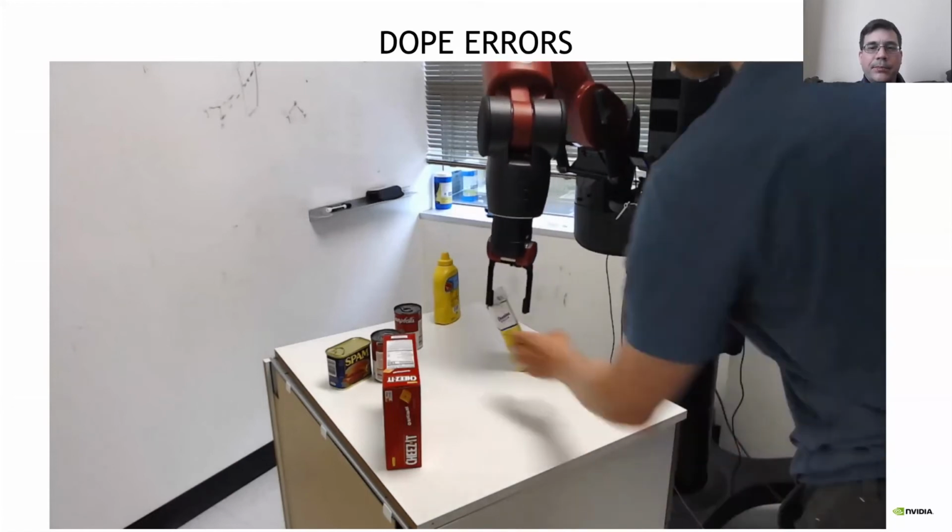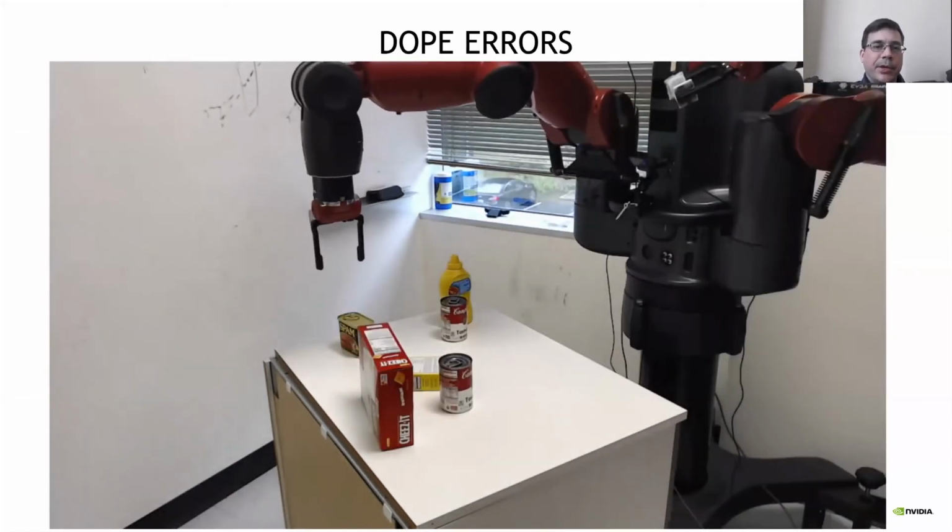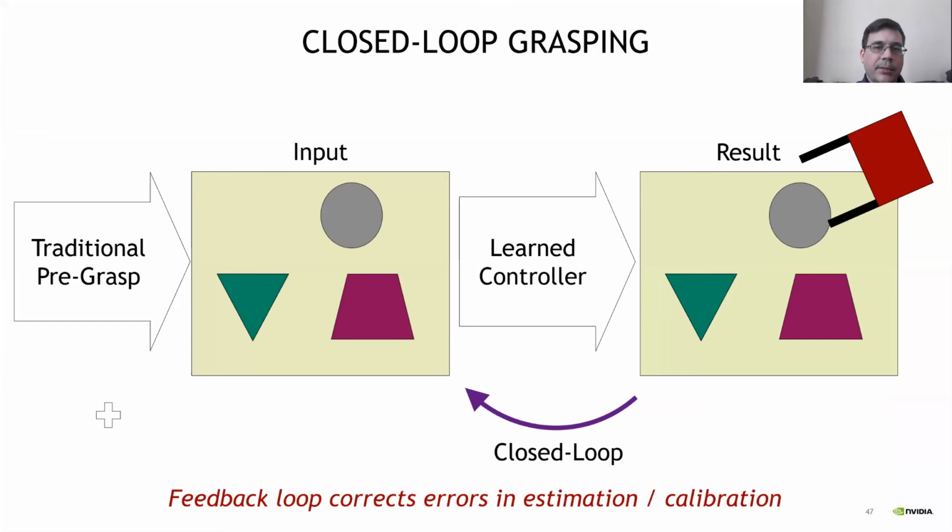And so we asked ourselves whether there wasn't something we could do to make this better. What we came up with is a solution for closed-loop grasping. In this case, we use images from the camera to constantly feed back into the network to correct the errors in calibration or estimation. We still use DOPE for the pre-grasp, and after that, the closed-loop processing allows the network to continually adjust itself.